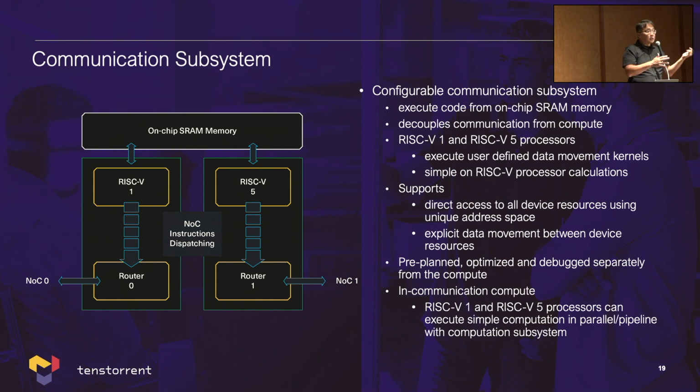And the nice thing about this is that we're also using the RISC-V instruction set, right? We have the RISC-V extension for our matrix engine and tensor engine. However, all of the other things are compatible with the existing RISC-V toolchain. So the nice thing is that you can write a C program, you can write whatever program you want to program this thing. Do whatever you want to do. So it's very convenient. You have conformity to the RISC-V architecture, but at the same time you also get the flexibility for the extension.